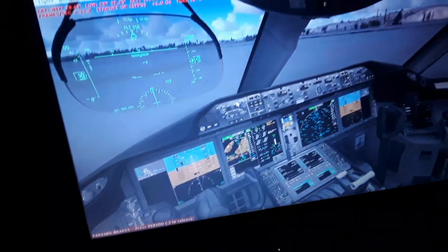We have also the angle of attack of the aircraft as it flies and the flight modes with the autopilot, the autothrottle, and vertical navigation modes. We have also the navigation display. The navigation display displays the inertial reference position, the GPS position of the aircraft, the terrain and weather reflections from the weather radar. You can see also the horizontal and the vertical profile of the aircraft flight plan.